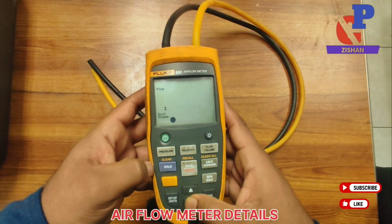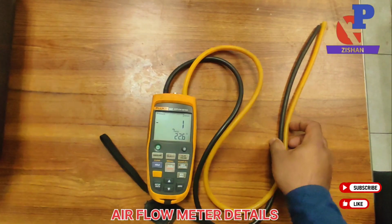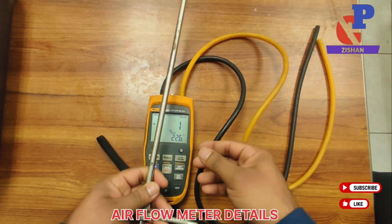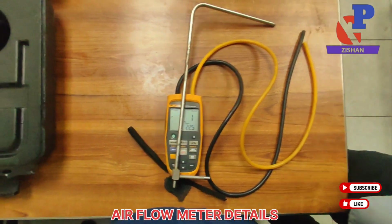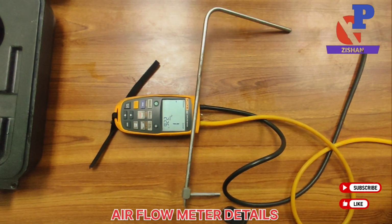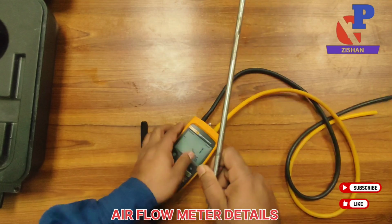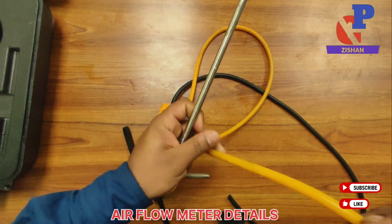Similarly we can take the differential pressure across the coil also. Before the coil we have to connect the positive hose, and after the coil we have to connect the negative hose. For the blower, the pressure increases across it, that's why we have to connect the black hose before the blower and the positive hose after the blower, so that we can take the differential pressure reading.